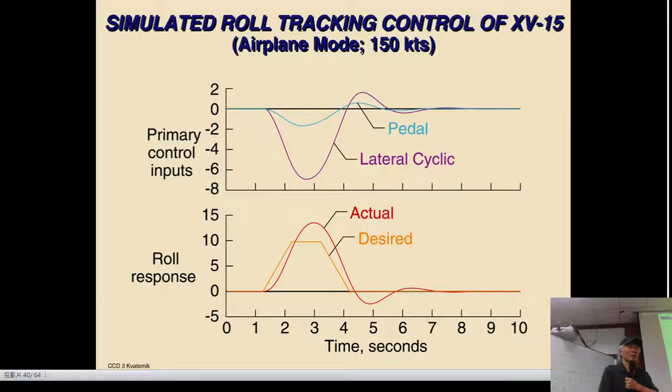For example, if I have desired eigenvalues, will my pole placement technique allow you to get the desired eigenvalues? Yes or no? Under only one condition, for a controllable system, you can always achieve the desired eigenvalue, but it has to be a controllable system.